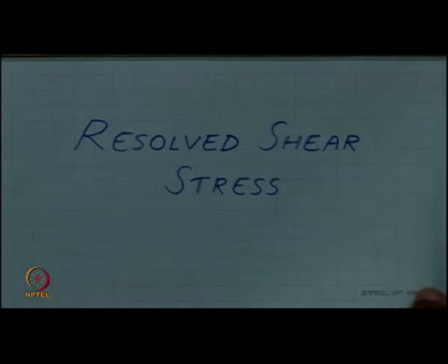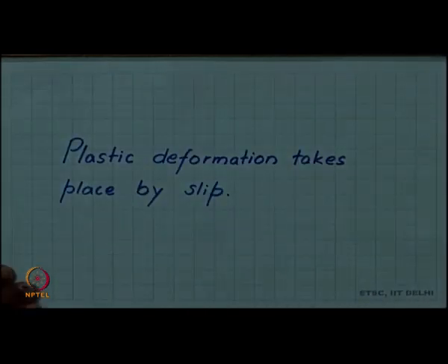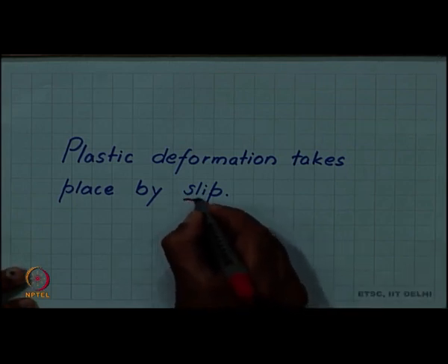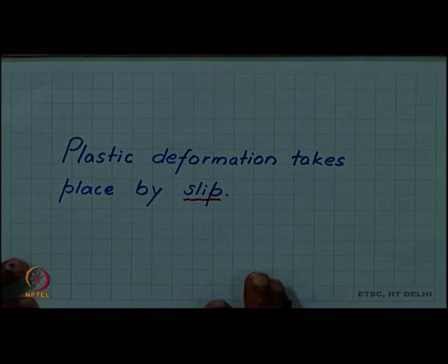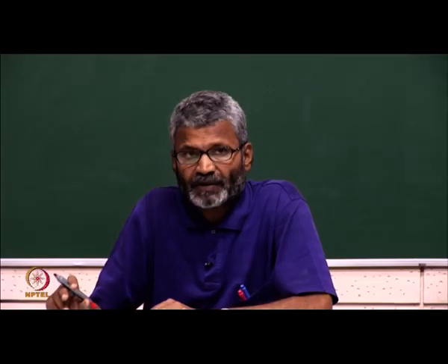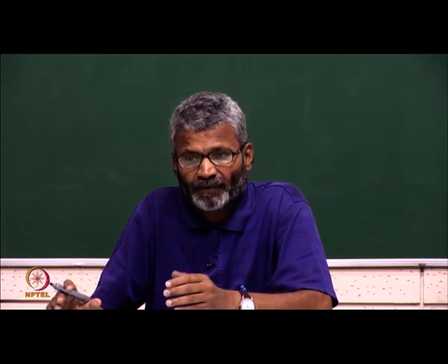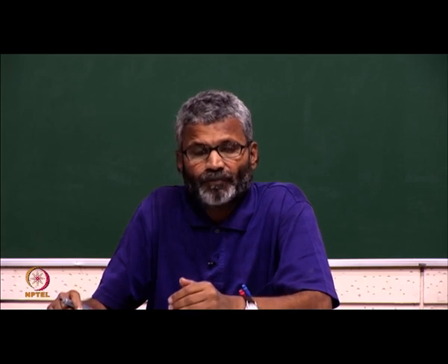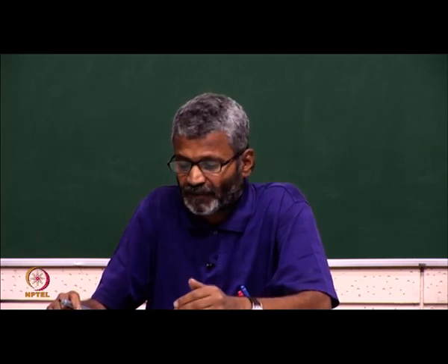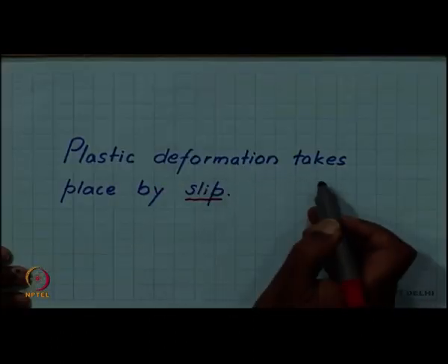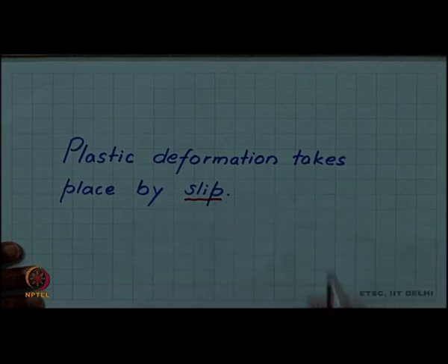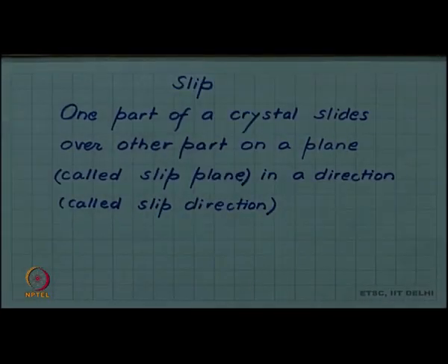Let us discuss an important concept called resolved shear stress, which will help us in understanding plastic deformation. We have already seen that plastic deformation takes place by slip. This was to explain why there is no change in the crystal structure of the material during plastic deformation. Although there is a macroscopic shape change, internally the unit cell does not deform; the crystal structure remains the same. To explain that, plastic deformation was understood to take place by slip, and by slip we meant that